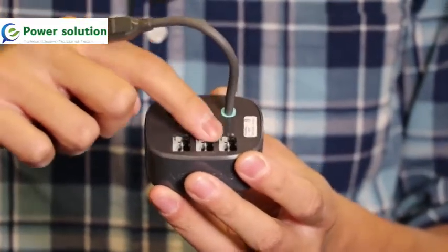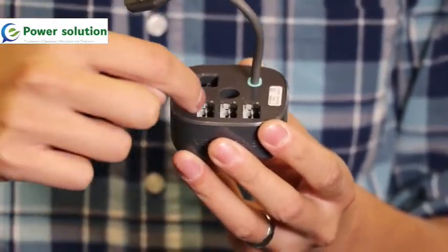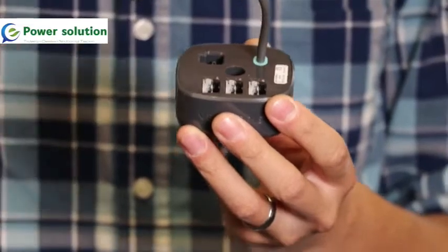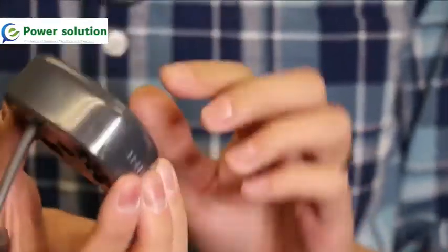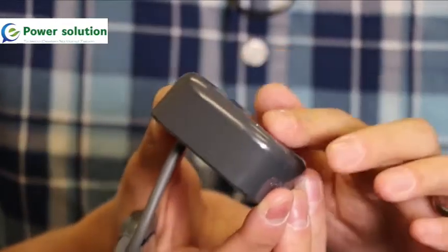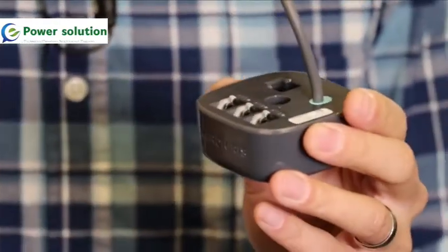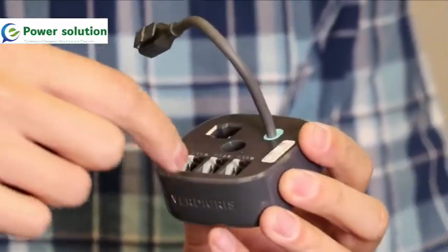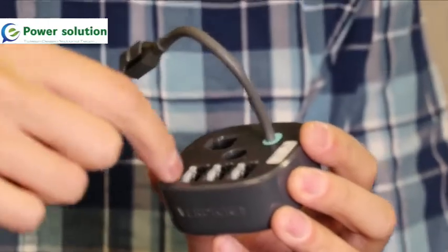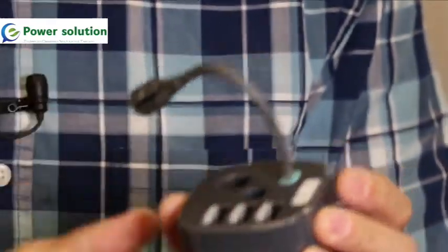There are 3 sensor ports that will take the positive and negative leads from your off-the-shelf CT. There is a magnetic backing on it that will attach to the panel board. And when you seat the CTs in, don't forget to put the darker wire in the black socket and the lighter wire in the gray socket.